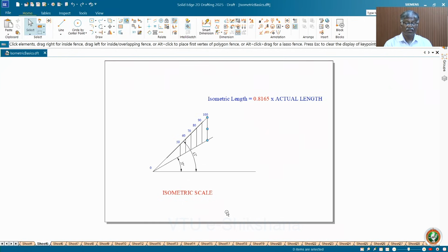You have to draw a circle as the projection, just like a point projection. You look from any direction, you will get a point, something like that. It is a sphere of true diameter, you have to draw it, but to fix the height, you have to fix the isometric heights, the height of the center of the sphere, etc. Otherwise, the actual sphere dimension is used.